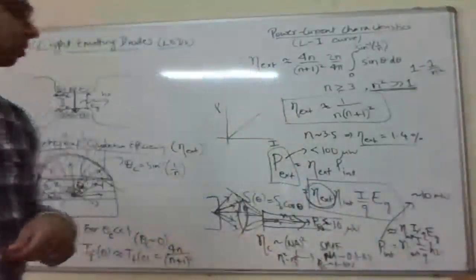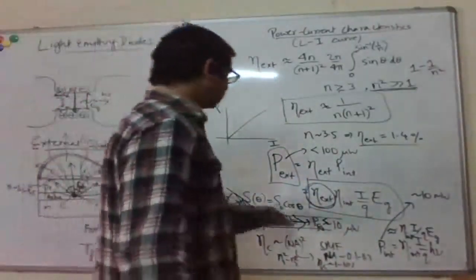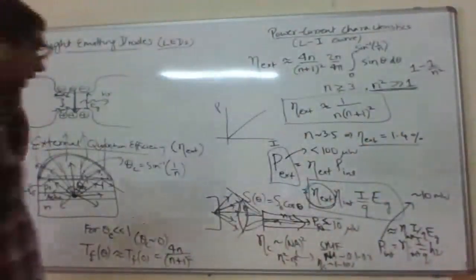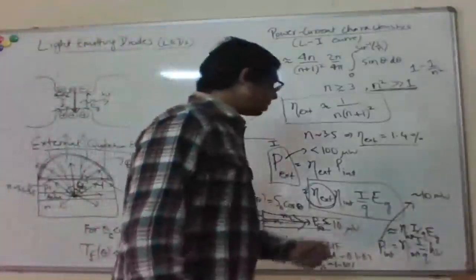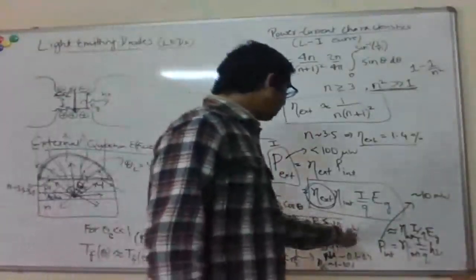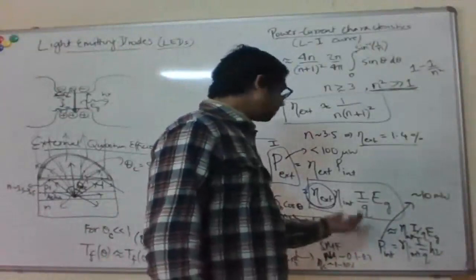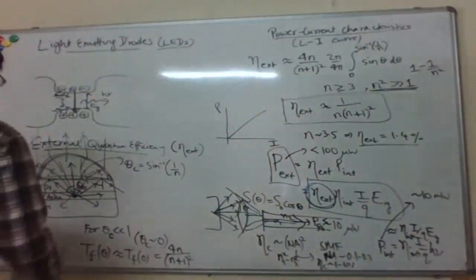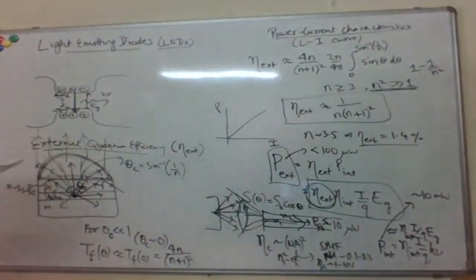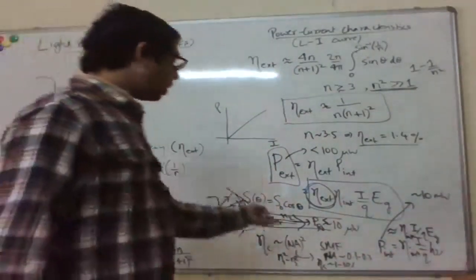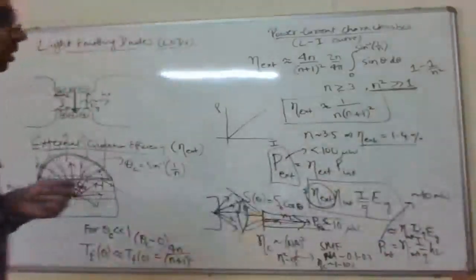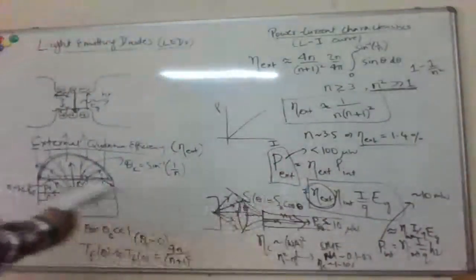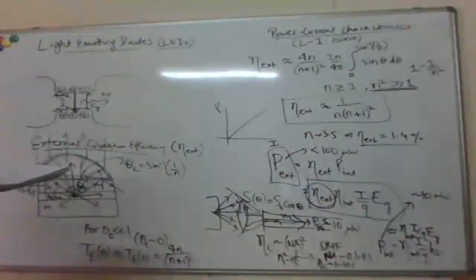Okay, so with LEDs, that's the kind of powers you're looking at in your fiber for communication. So you can see that that's really tiny, right? So with lasers, we typically work with tens of milliwatts. With LEDs, we are talking about microwatts, so 3 orders of magnitude lower. Right, and not only that, you have lower power and also it's spread over broader bandwidth, right? So for example, you get more dispersion, more dispersive broadening as you go into the fiber.